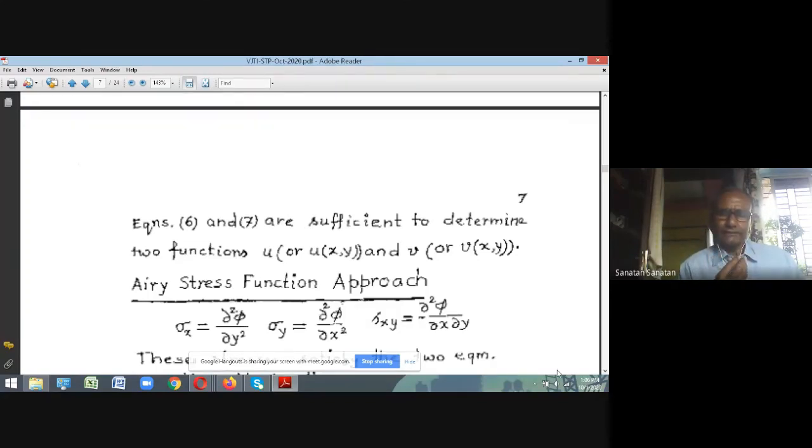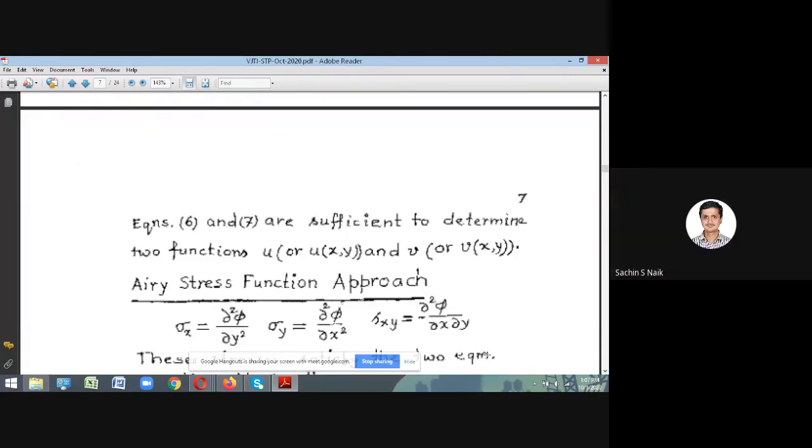And in order to overcome the statical indeterminacy, you have to bring in the deformation condition that u1 equals u2. So this problem is statically indeterminate. From the equilibrium equations, you couldn't determine RA and RB, but by bringing in the displacement conditions or compatibility conditions, you get some linkage between RA and RB, and then you are able to solve for both RA and RB. So that's what it is, compatibility conditions and statical indeterminacy. I hope I am clear now.